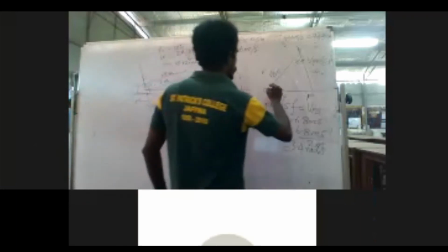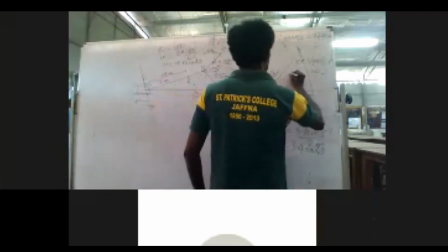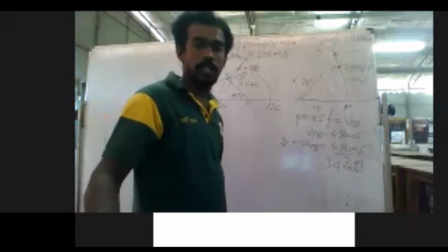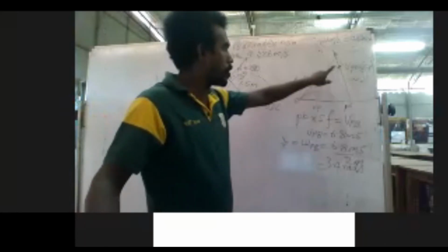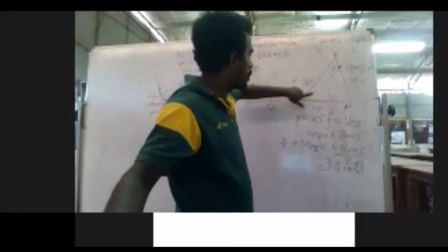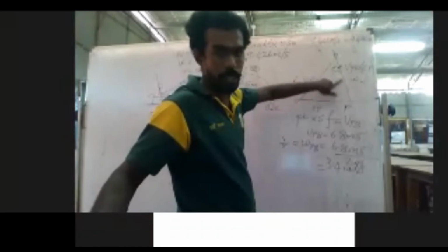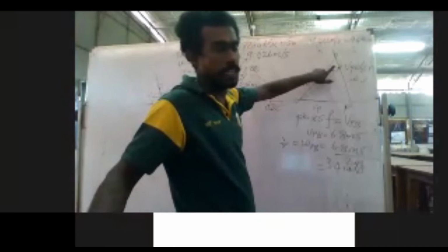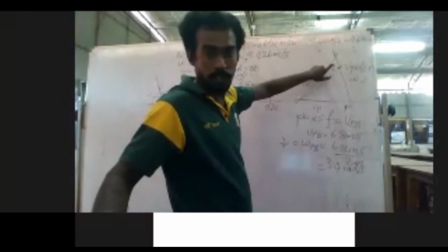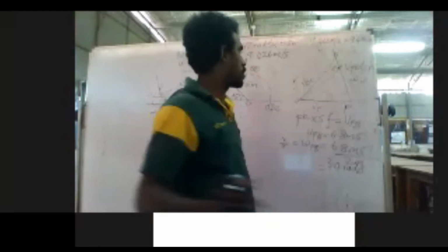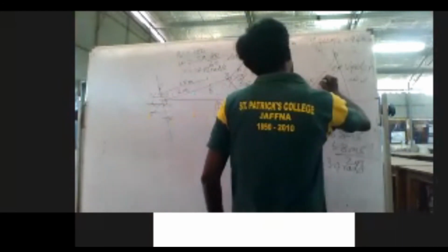Now I will join this. Now we can find the velocity of point E on the connecting rod, 1.5 meter from the gudgeon pin. That is the BE vector, right? Again, we need to measure it. So here is our BE vector.